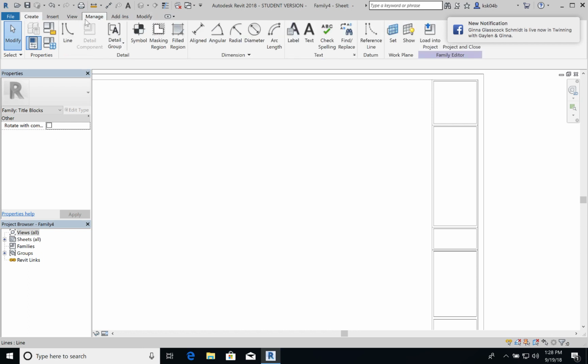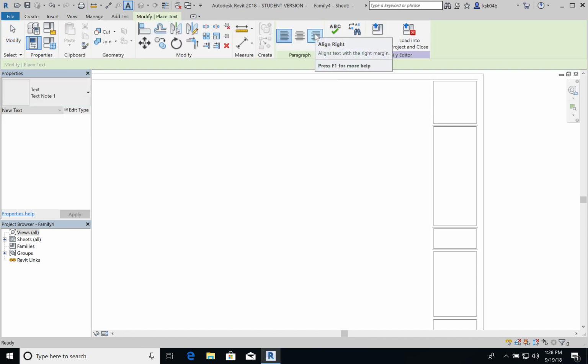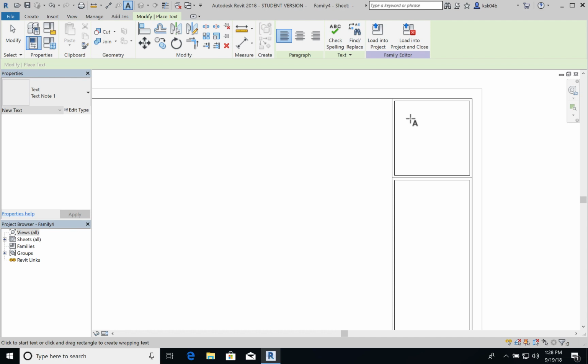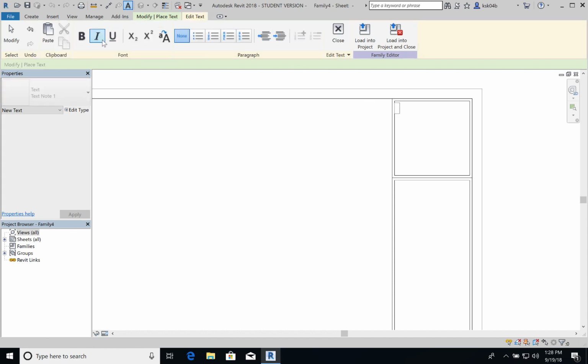the text objects. So go in here and you will click, you have the option of providing text, or you can do a label. So the difference here is, if there is something that I want written on every sheet all the time, maybe it's my name, then I'm going to choose text, and here I'm going to place that text wherever I want it, and then you can modify the size and the boldness and the formatting, all of that here on that.